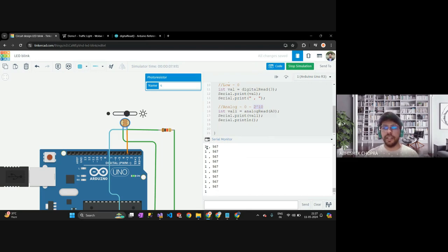That is the threshold. But in real life that would not be the case, since I told you there would be noise. I'll cover what kind of noise we'll be facing here and how to filter that in later sessions. We can see we are getting analog values, and this went to a maximum of 679. It might be due to the resistance or something here.